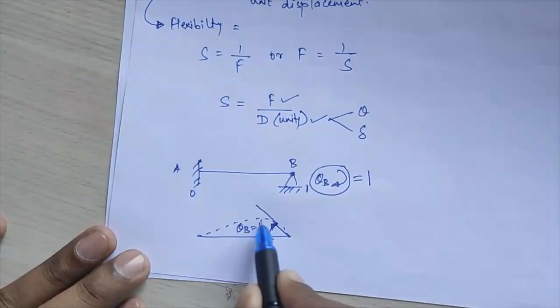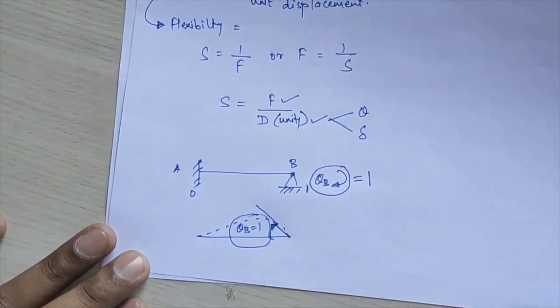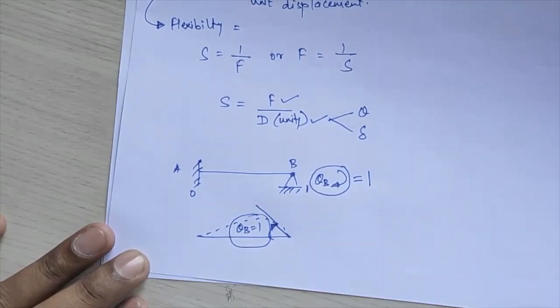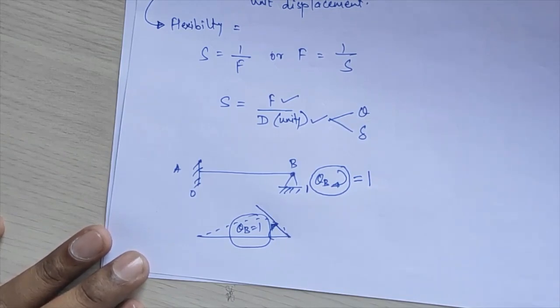So what you have to do here is assume the slopes and the deflections as the translational displacements, and you have to assume those as unity initially. Like in the flexibility matrix method, where we assume forces and moments as redundants, here you have to apply theta and delta as your redundant displacements, or that will be called your non-zero joint displacements.